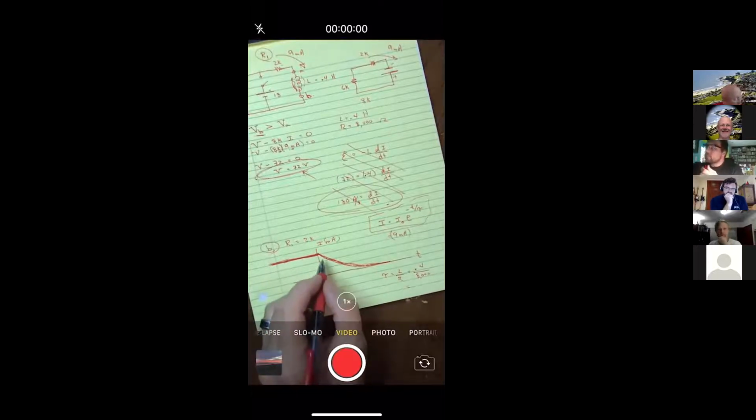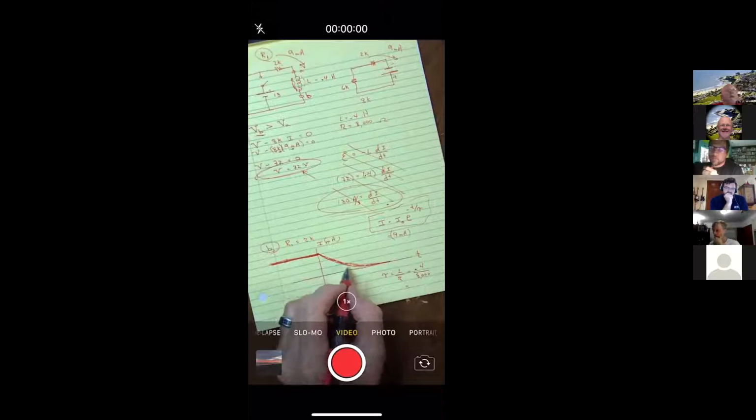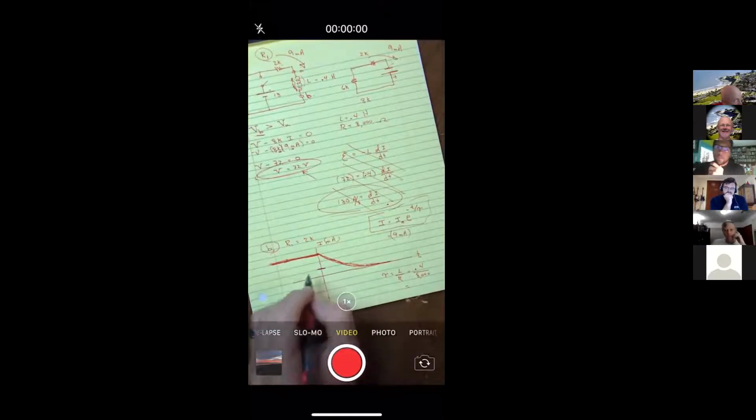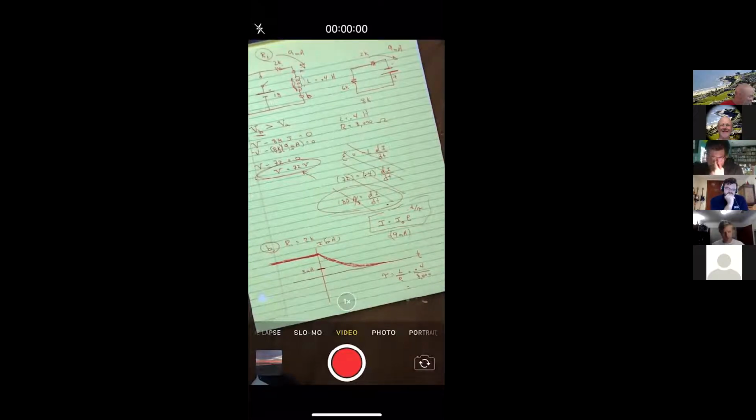Well, actually, maybe I'll do this. I know that it drops down by 63%, which is about 2/3. So it's going to be at about 3 milliamps in one decay constant. Wait, I think I said that wrong. Let me try that. E to the -1 should be about 0.37. So that's about 1/3. Yeah, 1/3 left over. Okay, yeah, I did say it right.